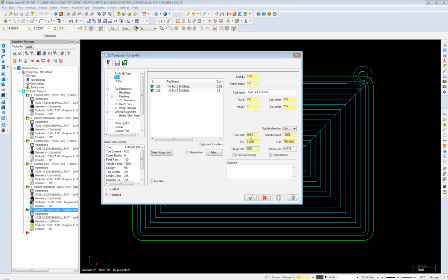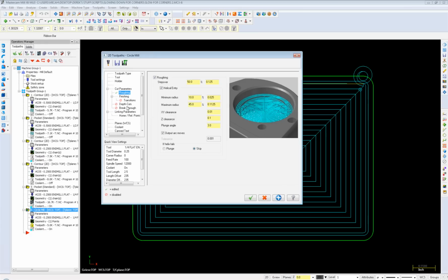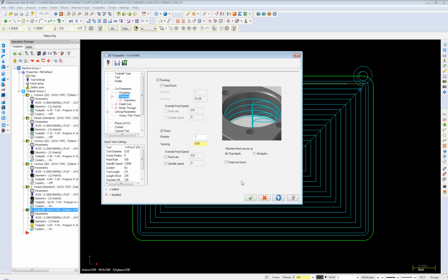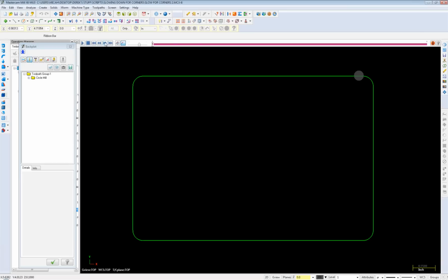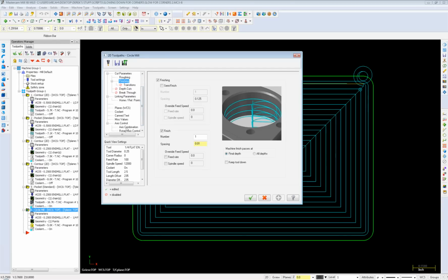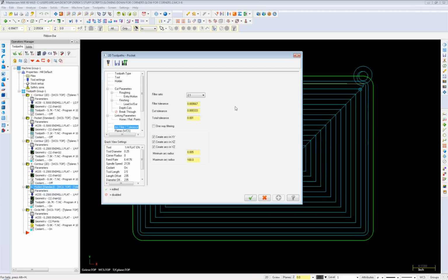So I set it up with a feed rate of 100 inches a minute and a plunge rate of 50 inches a minute, and we're cutting a 3/4 inch diameter circle. I made a roughing pass and one finish pass of 10 thousandths. When I backplotted it without applying the high feed, it did the whole thing at 100 inches a minute. After I applied the high feed and backplotted it, it's doing its helical entry at 21 inches a minute, and then as it arcs out, you can see it spiraling out, it gets up to 33 inches a minute to cut the actual circle out. Right. So could you just show that checkbox one more time there, Micah, the override feed rate?